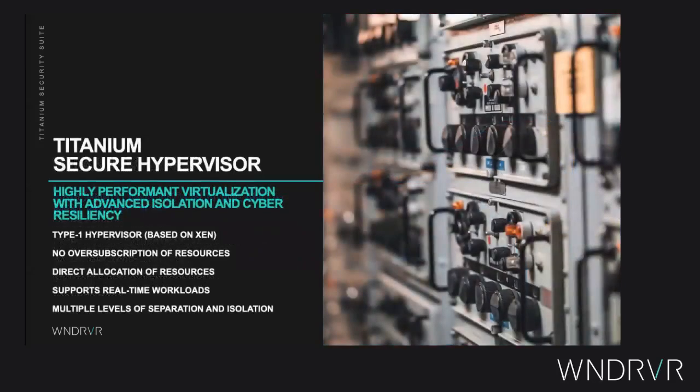Next, we have our Titanium Secure Hypervisor. I mentioned this was for Intel. If you need a solution for ARM devices, Wind River does have its Helix virtualization platform that would be an option there. But on the Intel side, we can run our Type 1 hypervisor that's based on Xen. We can run it on, again, Intel Broadwell or newer chipsets with at least 4 cores.